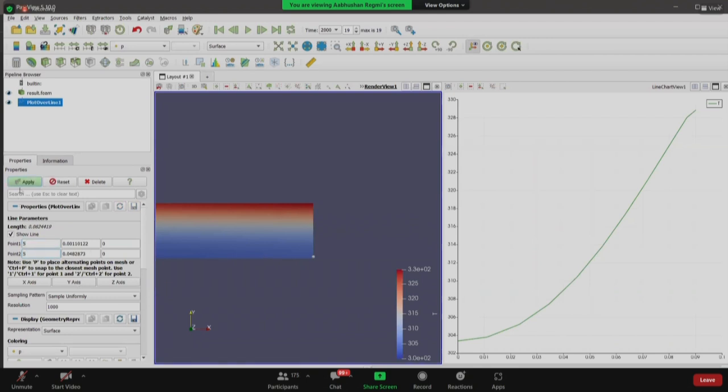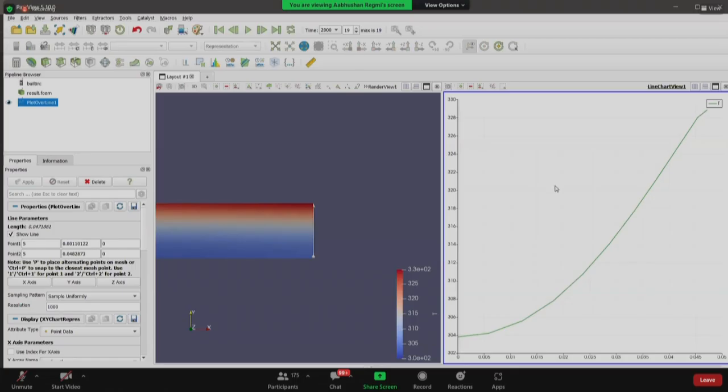Hello, sir. Yeah, I have a general question. I was using OpenFOAM version 10, and I ran your solver. The thing is that there is no buoyantSimpleFoam over there. It has been replaced by a general solver, buoyantFoam. Now the same code which you have provided, I'm not able to solve using this particular solver in OpenFOAM 10.